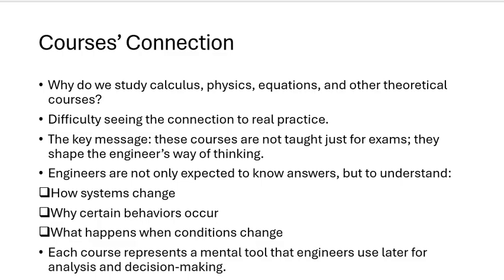So when concrete is fresh, we just pour it. When it becomes hard, then you put water on it or apply something wet on it. Why are we doing this? To take care of this reaction. If you don't decrease the heat, cracks will start appearing in the concrete from the start. Got it? So again, coming from science.